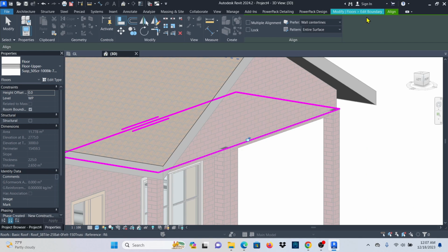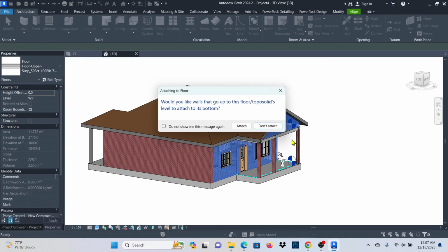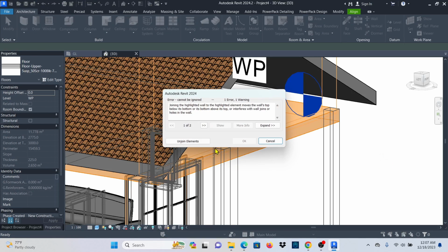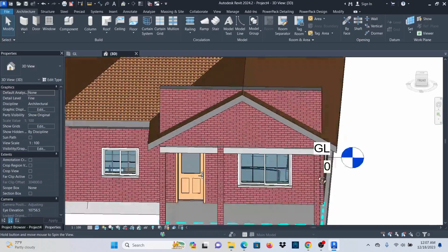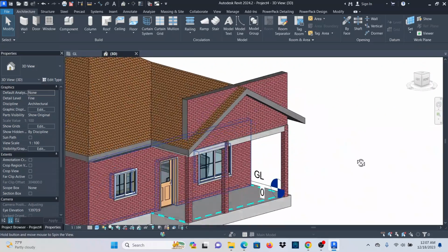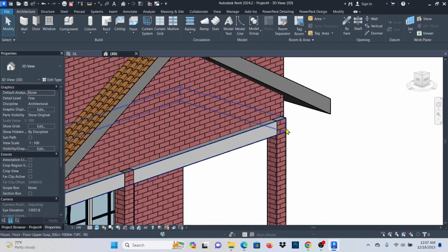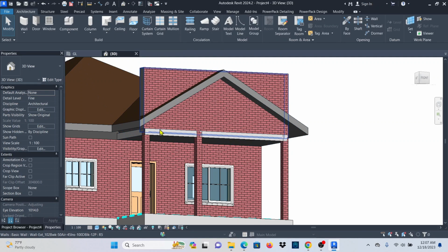Select that one, then go to edit there so that you can see the green check mark. Maybe let me use attach and join elements. Click outside, and you see that we have that one there. Okay, now if I want, I can even make sure that it goes outside. It's just a detail. If I want, I can even move it above.